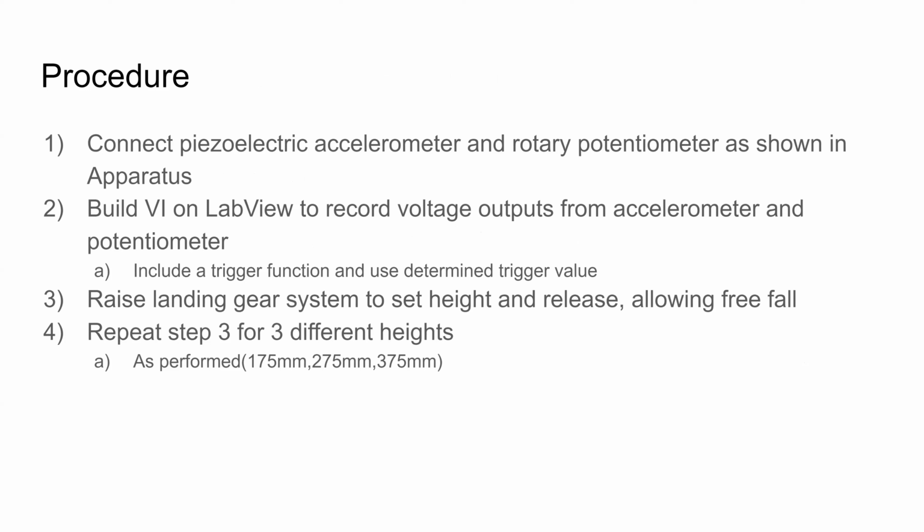And then the procedure for the drop part of the lab, where we're actually dropping the landing gear. First we connected the accelerometer and rotary potentiometer, as I just showed in the apparatus. Again, the VI we previously showed, built in LabVIEW, records voltage outputs from the accelerometer and potentiometer. It also records the voltage output from the photodiode, but that's more just used as a trigger to start the recording. So when that trigger value is crossed, the automated system starts the value recordings of both acceleration and